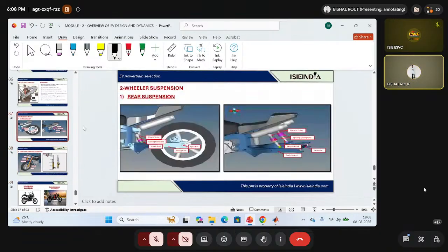Like you can see, this is what is called a swing arm. The swing arm has a specific design. The spindle connecting the swing arm has a specific design. We have to understand how the spindle needs to be taken, and what the length of this swing arm is. Basically, the swing arm is connecting your vehicle to this particular thing. This is the swing arm. Your tires are connected to the chassis with the help of the swing arm. The swing arm needs to be calculated by formulas, right? If your swing arm length is high or low, then you get a higher or lower force coming from the road. So the swing arm is again calculated by a certain technology, by MATLAB also.